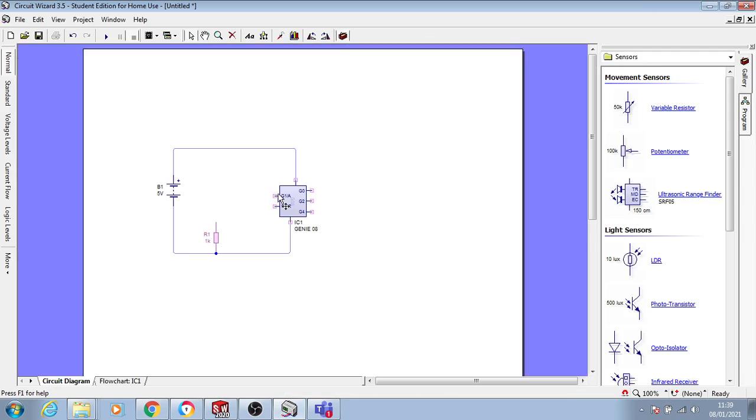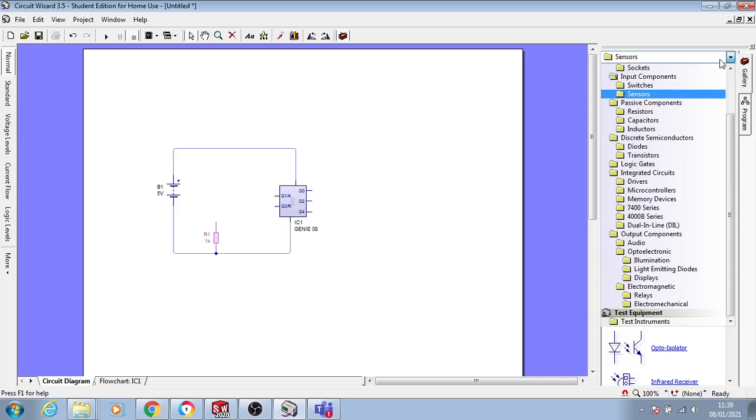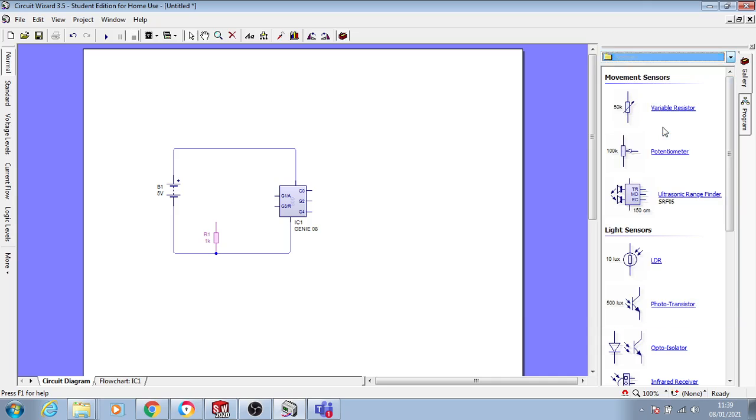And so if you're drawing this potential divider, it depends which way round you have this light sensor. So I'll do that as an example just so that we'll keep that relevant. So we'll go to those sensors and we'll just put an LDR there. Okay, and you might even have, this is a variable resistor, but you might also have an actual variable resistor here just so you can calibrate.